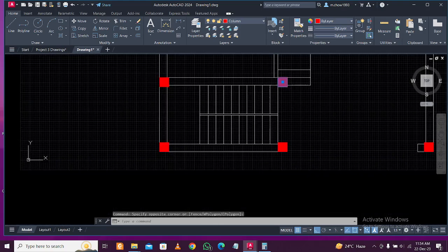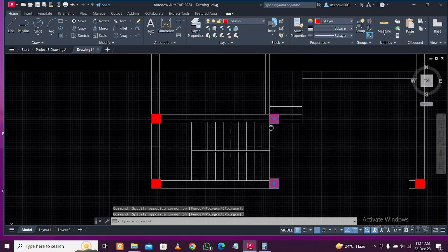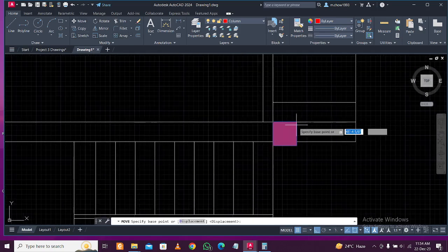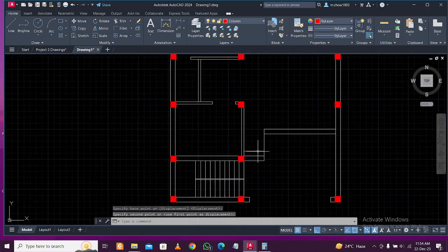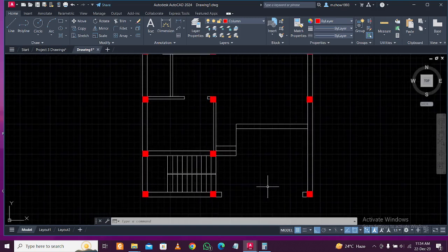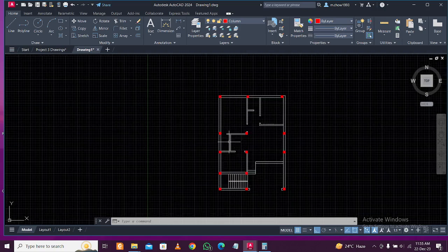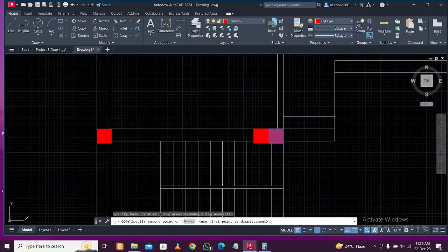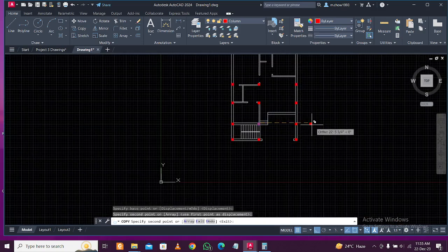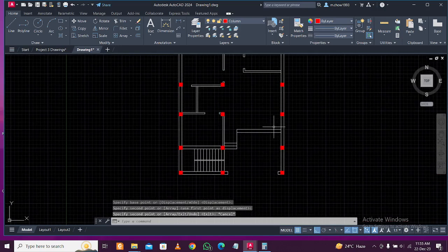Okay, and we'll also move this, so we'll have a uniform. This is the dream of a structural engineer, to have all the columns in the same line. So I'll just move this one here, so we'll have the columns along the same line here. And if you need a cantilever, you can get a cantilever on this side when you make the headroom, so there will be no problems in this portion. Okay, so this is the design. So one beam, and this also, if we give another one there, then it will be perfect for the beam. So you know, in a beam column plan, you'll understand how the beam works, but this is perfectly done.